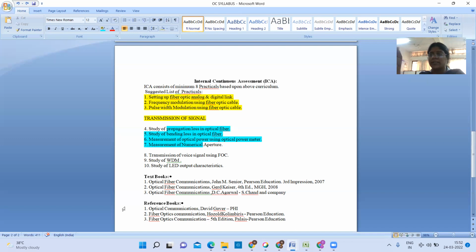Okay, so this is the optical fiber, light coming out of that optical fiber, and that end we will connect to this optical power meter. Okay, so this is the optical power meter. So the light coming out of this optical fiber is connected to this optical power meter. Here it is connected, and right now I have not turned it on. When you turn it on, the power reading will be displayed.